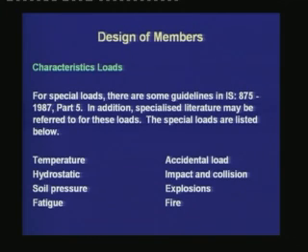The special loads are listed below: temperature, hydrostatic, soil pressure, fatigue, accidental load, impact and collision, explosions, fire. Thus, we see that for the special loads, IS 875 part 5 gives us some basic guidelines, but we may need specialized literature or international codes to get more detailed values for these special loads.